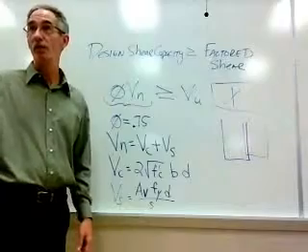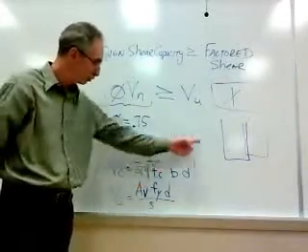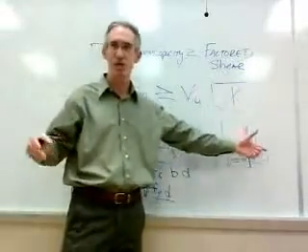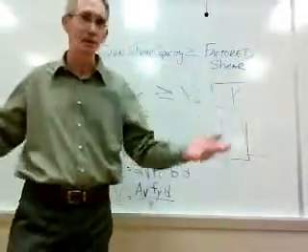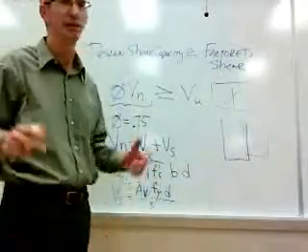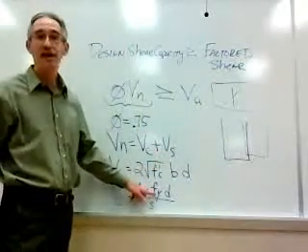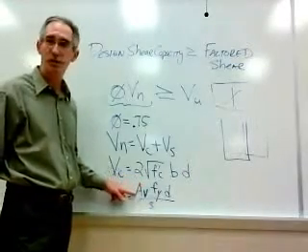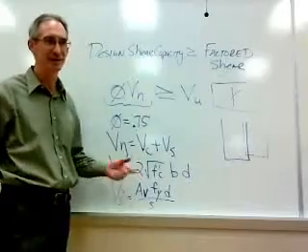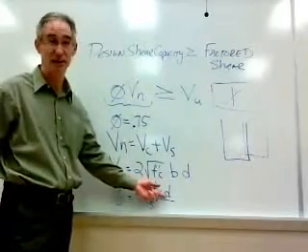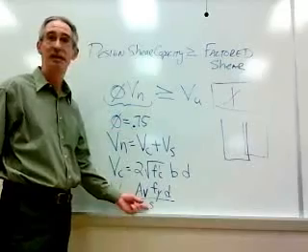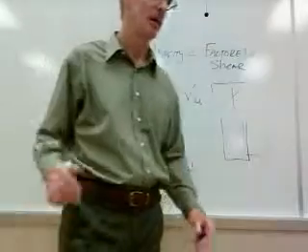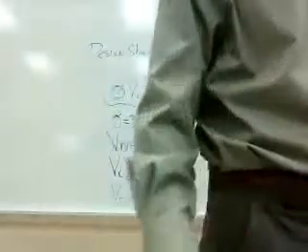The area of the bar times 2, right? Because there'd be 2 legs intercepting the crack. If you had a double stirrup, which I don't think you're going to have, but you could have 4, but that would be for a bigger beam. f_y, you know what f_y is, right? Yield strength of the stirrup steel. Again, it'll be the same yield strength as your regular steel. d, you know what that is. What's s? Spacing of the stirrups. Okay? So that's what we got going on there.